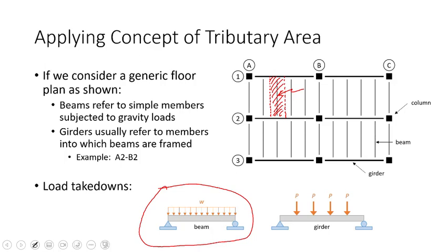I know things. So, all right, if we're only considering gravity loads, making sure we're paying attention, what can you tell me about these edge beams versus these interior beams? They're responsible for less load. So if I'm a designer, what does that mean? It can be a smaller member, a smaller section. Exactly right.